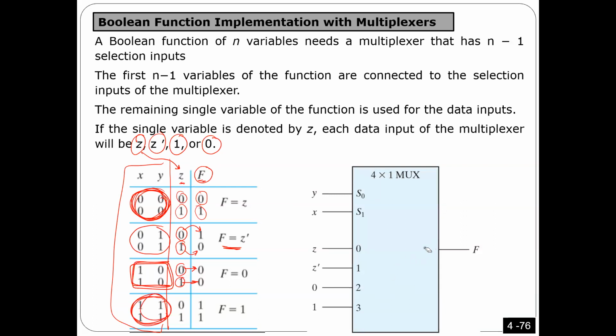Okay, so I'm gonna connect this one to this one this way. Now look here, what's gonna happen. When z equals 0, I have to get 1. When it is 1, I get 1. So no matter what value z has, I'm always gonna get 1, so I'm gonna put 1 here all the time.